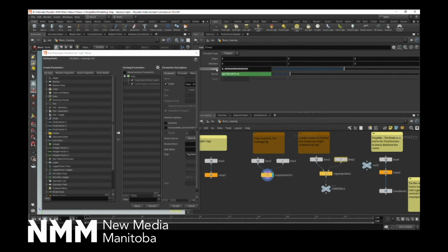I'm going to do the exact same thing. I'm just going to make a length here, but I get this problem while creating some requested parameters. Node is outside subnet. So it doesn't like the fact that this line is not really in the same subnet as this control node. I don't know, it's being a little fussy about it.